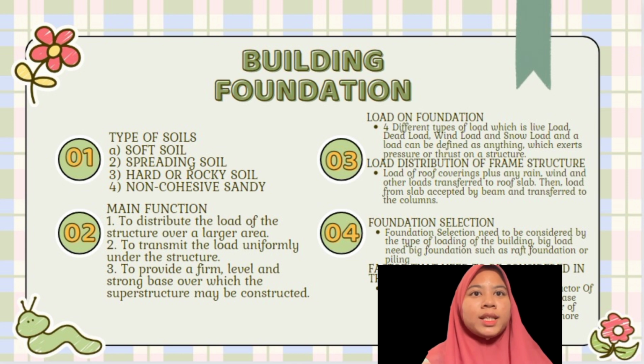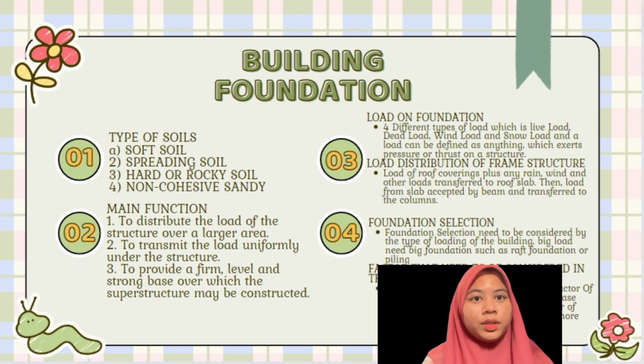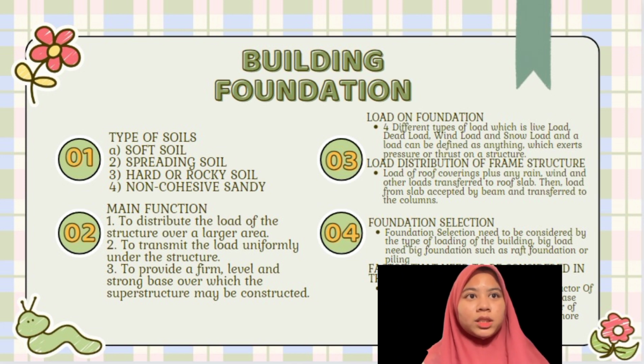The last one is non-cohesive sandy soil. These are subsoils that are less of a problem. They are unaffected by water and rely on the size, closeness of compaction or strength. The consolidation of non-cohesive soil occurs rapidly due to building load. Swelling on this type of soil is difficult to prove, but running groundwater will erode the fine particles, leaving the coarse material in an unstable condition. Usually if the water table is high, construction on non-cohesive subsoil will need the construction of drainage.